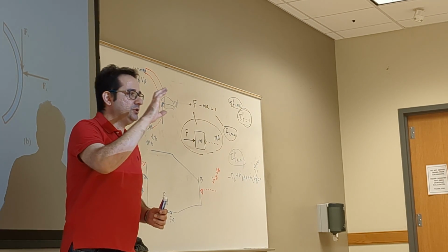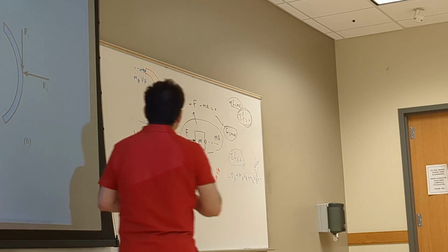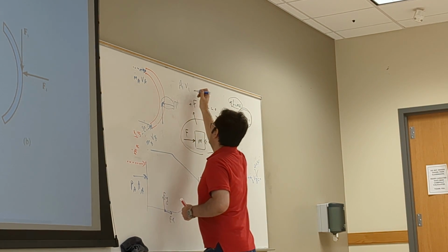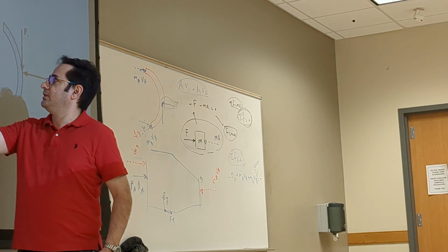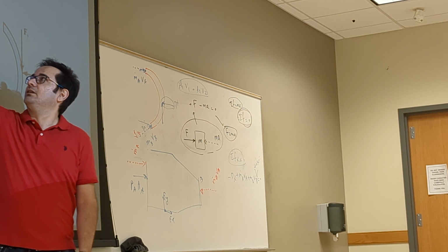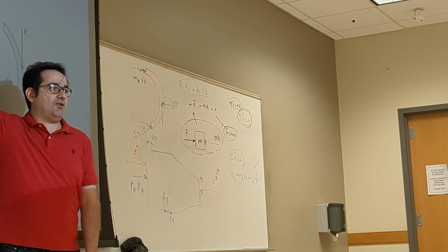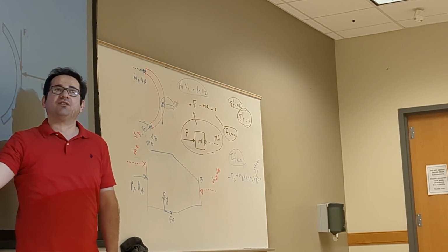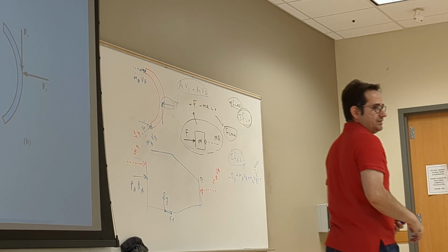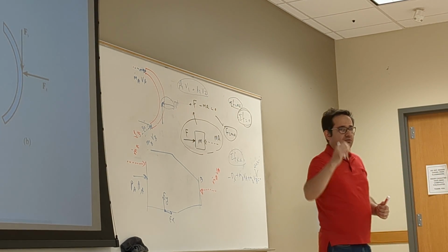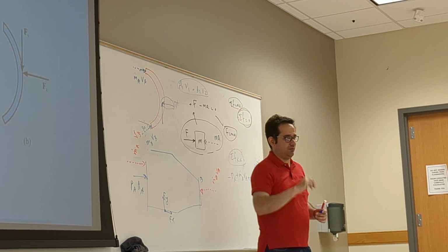On the other hand, from the continuity equation, conservation of mass, what do we have for AV? You see? AV is constant. A1 V1 is equal to A2 V2, right? Conservation of mass, anywhere along this stream. So you have the area times V, so that value is constant, so that means if velocity is constant everywhere, what can I say about area? The area is constant everywhere. That's it. Do not take anything for granted, always say, the only things I have are continuity, momentum, and Bernoulli. Three equations so far.